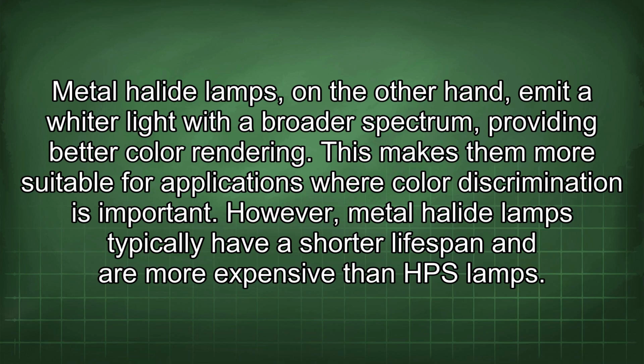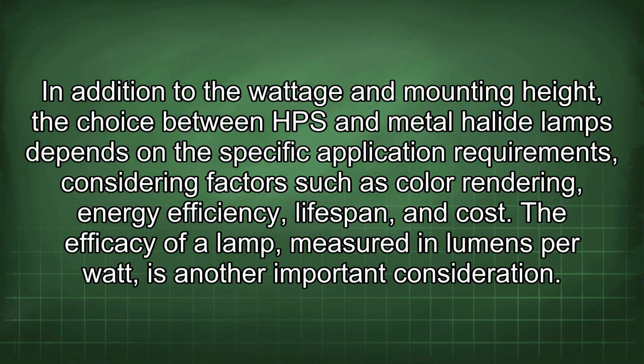However, metal halide lamps typically have a shorter lifespan and are more expensive than HPS lamps. In addition to the wattage and mounting height, the choice between HPS and metal halide lamps depends on the specific application requirements, considering factors such as color rendering, energy efficiency, lifespan, and cost.